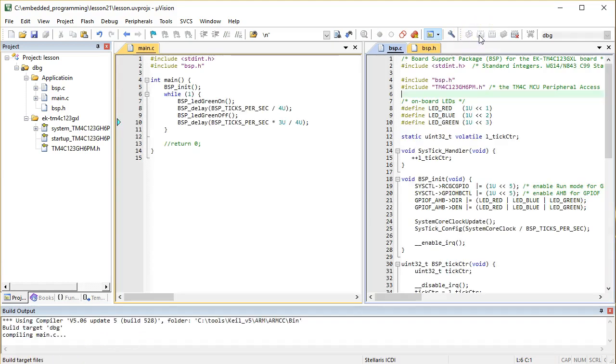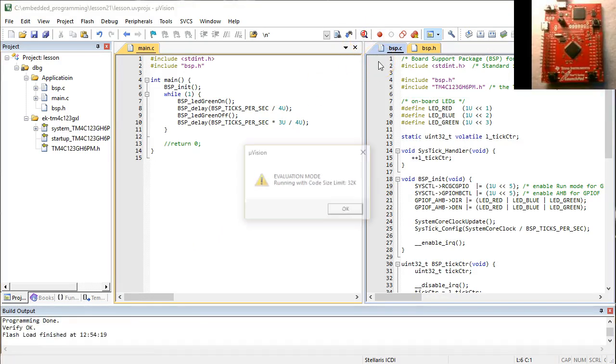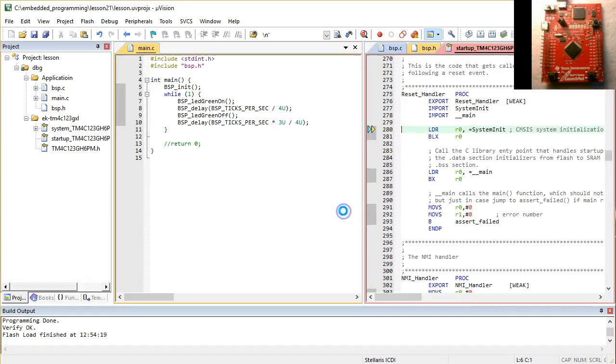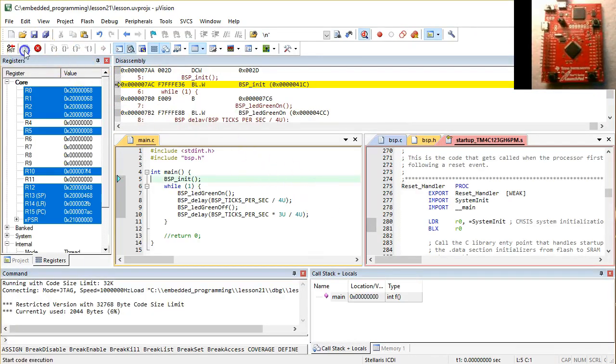As you can see, the code compiles and links error-free. The end effect is that your main code is completely insulated from the board. The background code only specifies what needs to be done, while the BSP code specifies how to do it. This way of separating concerns, the what from the how, has many advantages. First, your main code is smaller and self-explanatory. You really don't need comments to understand what's going on.